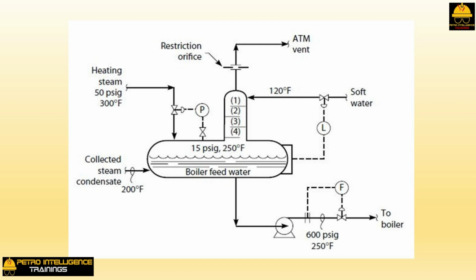X recommended to his boss that the softened water be preheated by using it on one side of a heat exchanger to cool off a waste-foul liquor stream that was flowing to the effluent treatment pond. This heated the softened water from 120 to 160 degrees Fahrenheit. The 50 psig steam demand was reduced by 25%. This reduced steam flow prevented the trays from flooding.